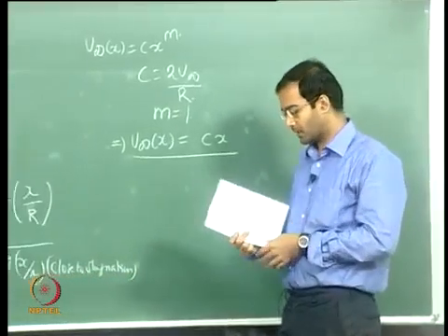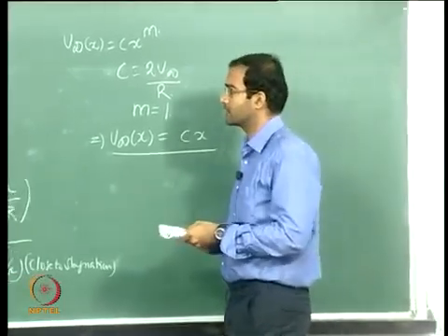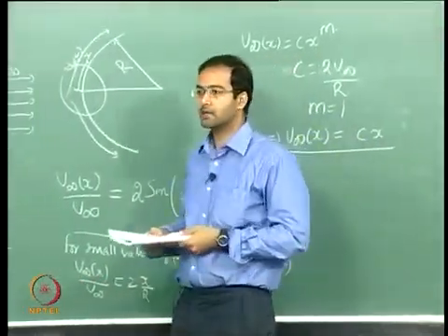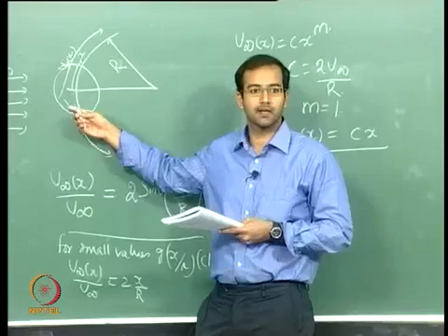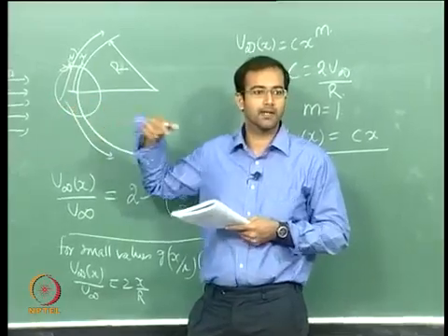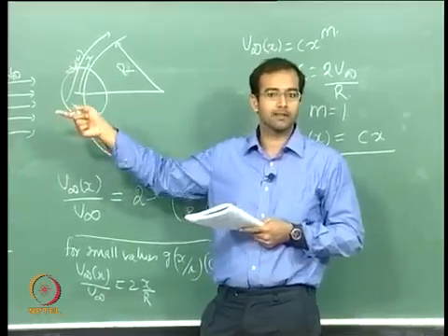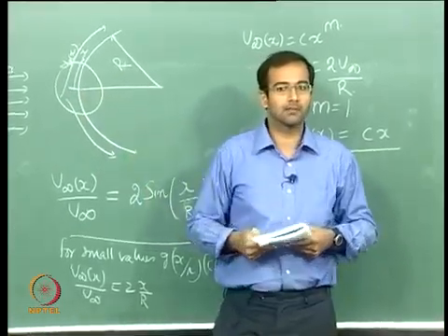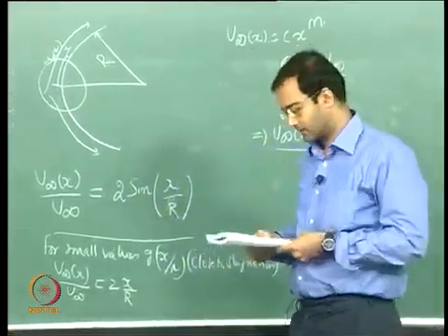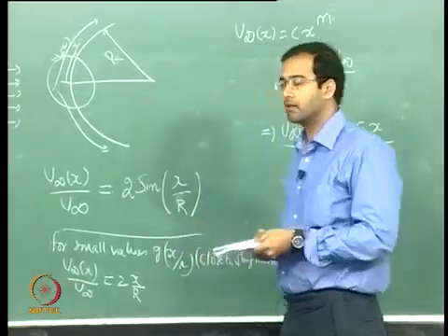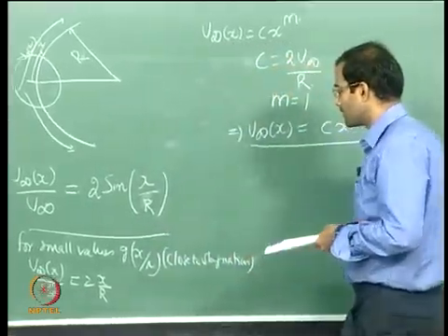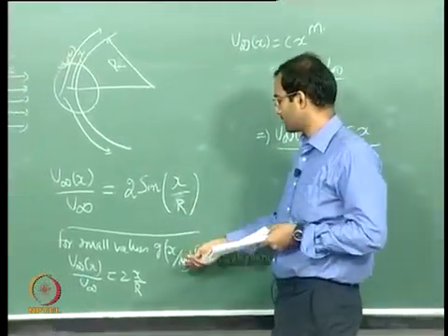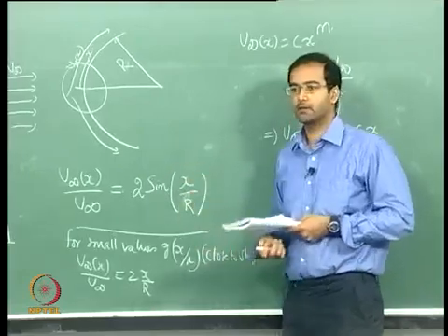So this is a very useful correlation, because to calculate, for example, the heat transfer in the stagnation region of a cylinder, you can solve the energy equation from the Falkner-Skan solution, and you can apply that to get the local Nusselt number profiles for the cylinder. So for small values of x, your sin theta can be replaced as theta.